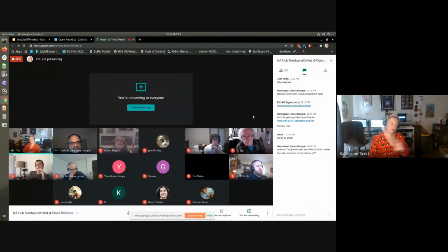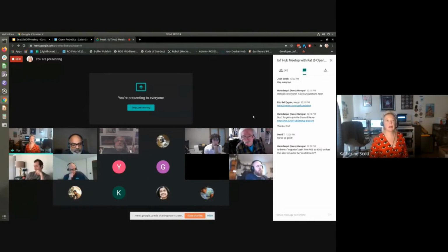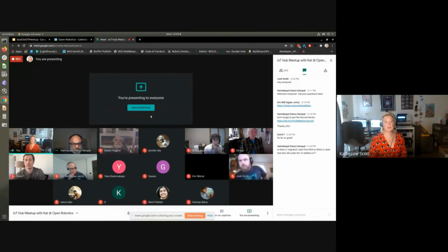So there is a rough migration path, which is to say I would personally recommend jumping up to Noetic, which is the last ROS 1 release, that ships with Python 3. Jump up to Noetic. That's a nice unit step of work. And then once you're at Noetic, jumping up to ROS 2 is just another release, more or less. I mean, there's some tooling. There's also the ROS 1 to ROS 2 bridge, which you can use if you're migrating a very large system. So you can move things over piecemeal, but that's generally the process I recommend.